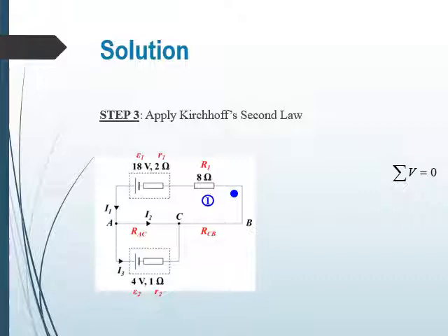If it moves to the left in the anti-clockwise direction, it will pass through the external resistor and the EMF1 with internal resistance r1. Now, as the loop passes through R1 and the internal resistance r1, it will experience a potential drop.